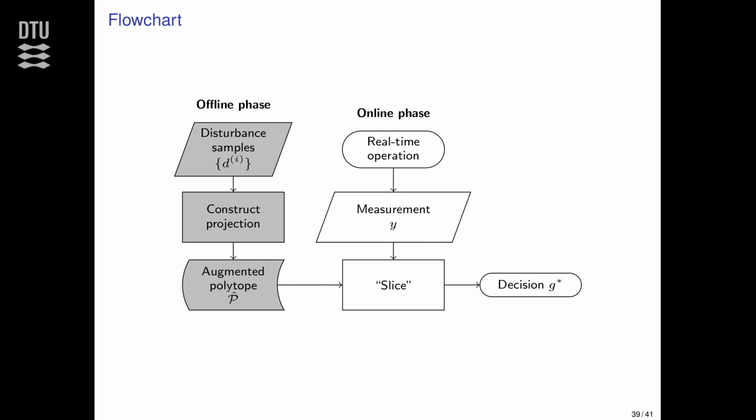And so this part here, the white part here, is a 1 millisecond thing. And it's a 1 millisecond thing where the only data you need to store here and use, it's 12 constraints, right? So it's something you could have in your microcontroller, right? While the part here is something that the distribution system operator has to do when he has all the data from the last 6 months, process them, remove constraints, and so on and so forth. Okay.